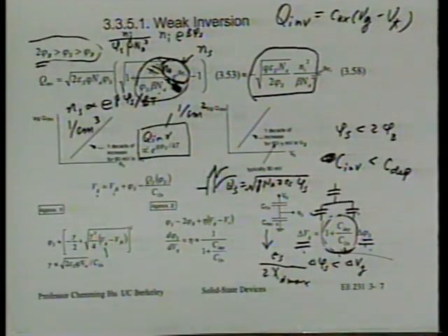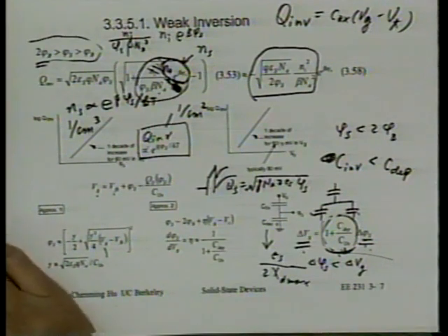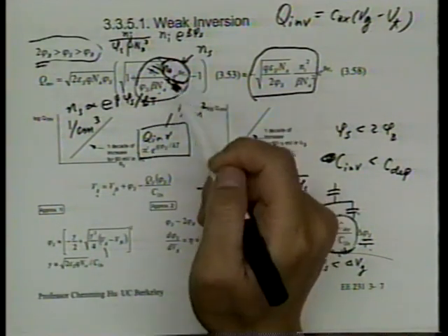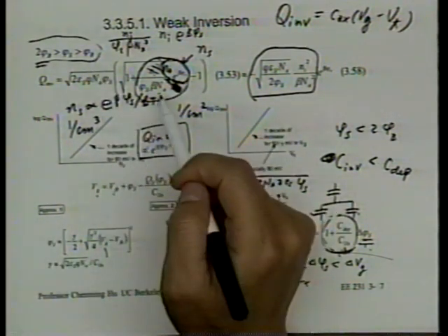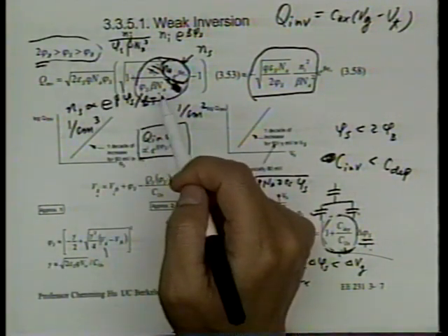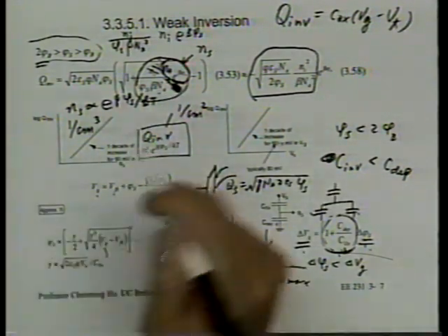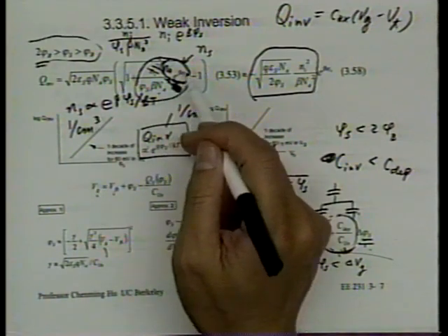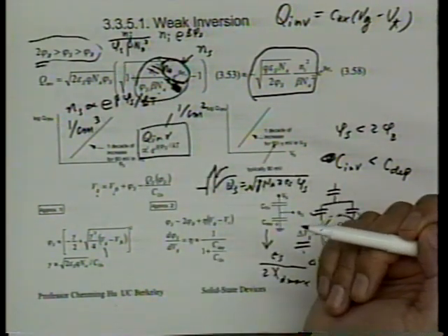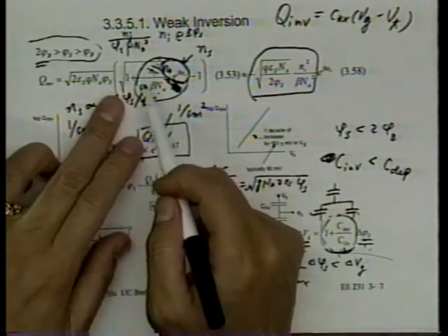We are in the inversion, but not strong inversion. So do you expect the electron concentration to be much larger than, much smaller than? Smaller than, correct. Because when it's equal to 2 phi b, we'll be equal to Na, right? So if we're 0.1 volt less than the 2 phi b, then Ns will be 2 orders of magnitude smaller, right? So the approximation, therefore, is not to ignore 1.